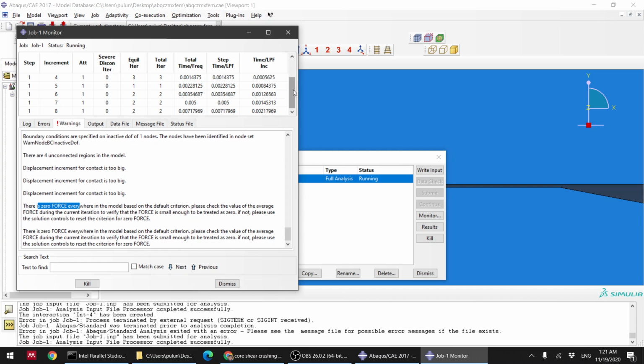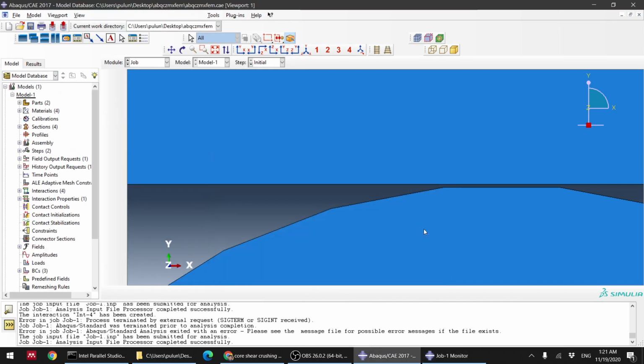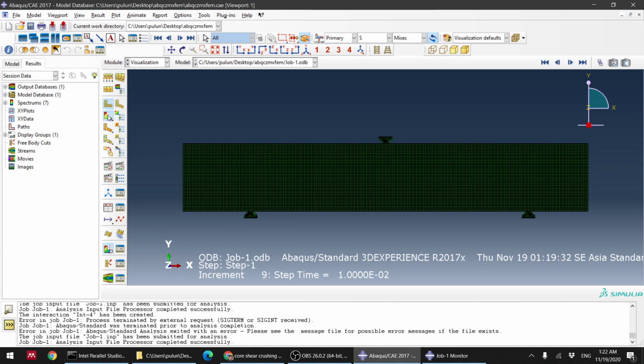But you see here in the beginning it is 0.001. They cut the time step 4 times and then they increase again. They start to stabilize, increasing 0.005, 0.08, 0.01, 0.1. Yeah, now it's increasing again. So now we have our first plot, I think, right? Our first frame. You can already check the result.